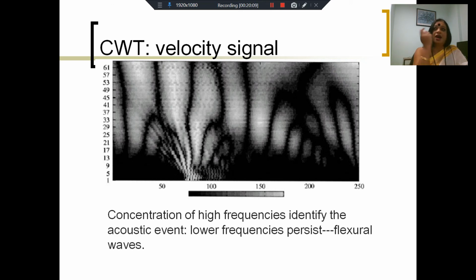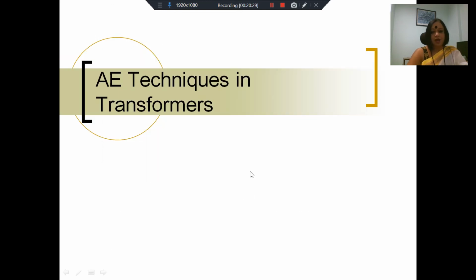Because they are not spread over a wide range, we will be able to identify in time exactly when this emission took place, and from the time-space correlation we will also be able to locate in space where the PD discharge occurs. So sometimes this kind of time information can be useful to us.